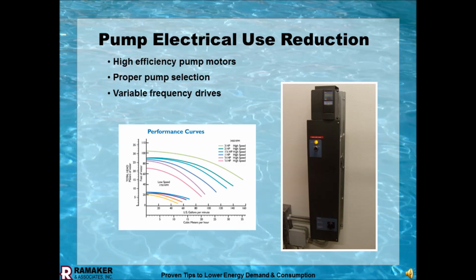Proper pump selection. The engineer, the designer should be doing calculations on what the head loss is going to be to pick the correct pump out so you're not deadheading. I will have to say this, though. In the past, because of VFDs not readily being available or not using them because of the cost issues, engineers did design conservative. I did it, and I'm not the only one.